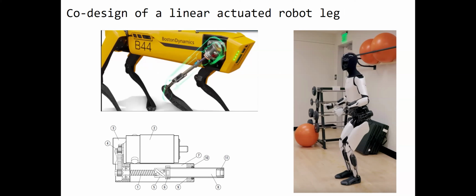For example, for Boston Dynamics Spot robot, this robot uses a kind of tricky design for the leg. Instead of using just 3 degrees of freedom with 3 motors attached on each part of the leg, for example, one motor of the hip which rolls the leg, one motor which makes the hip go up and down, and the third motor put in the knee to move the lower limb up or down. The mechanical design of the leg is a bit trickier.